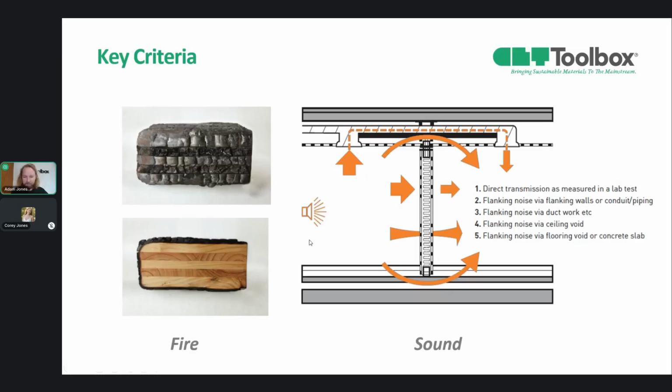So before we get into the structural design, it's always good to just touch on the multidisciplinary aspects. There's a lot of different things we could look at, including DFMA, durability, sustainability, but I think it's always fire and sound that comes specific and probably touches the structural engineer the most. So fire design point of view, we did do a webinar last month which covered this in detail, but the very simplistic version of it, when timber is exposed to fire, you do have a charring mechanism that reduces the capacity of the wall panel for the duration of the FRL. So that's one aspect that needs to be considered from the structural engineer, and we'll be covering that today with the fire design for a wall, but also sound as well.